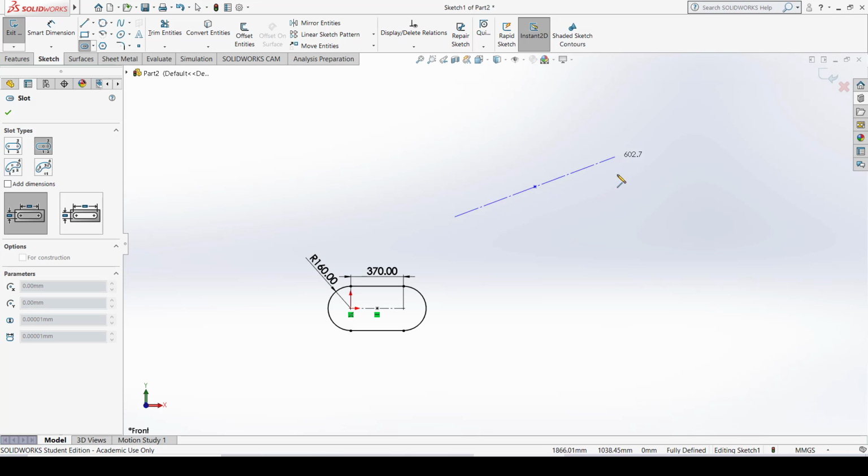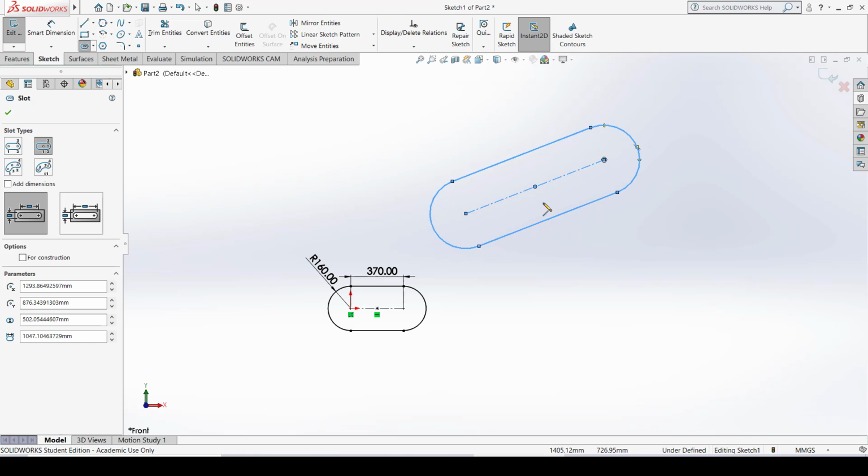Now at whatever inclination you want, you can give it anywhere in this direction, clockwise, anti-clockwise, any inclination. Let us say I just click here. You can drag your mouse anywhere else on the screen. So just click here. Okay, so this is the midpoint. From this midpoint your construction line expands in both directions with equal distance, and then you drag, just click here to end that command.